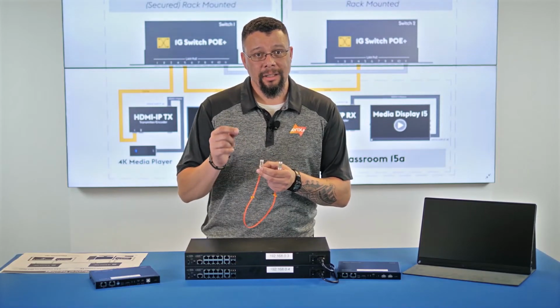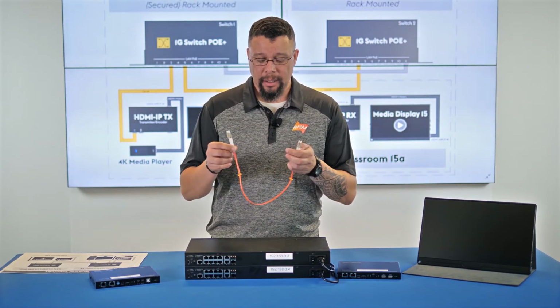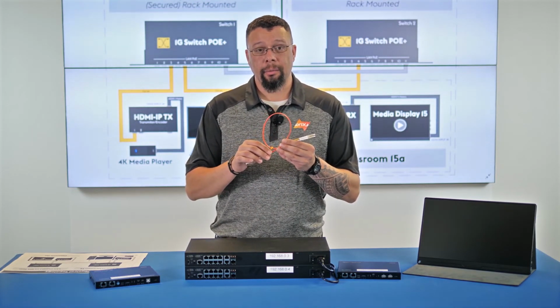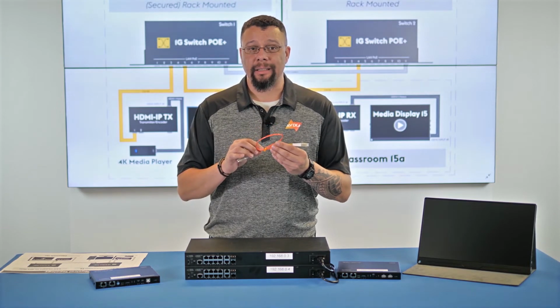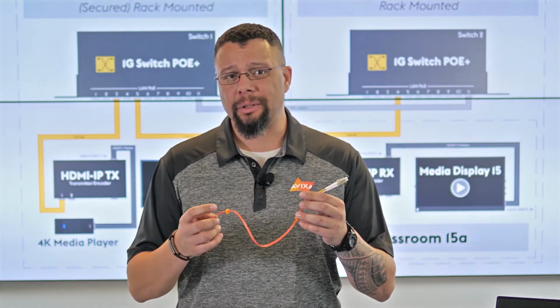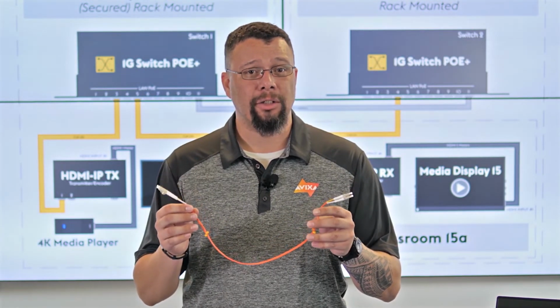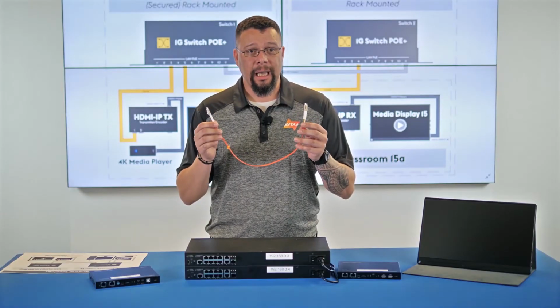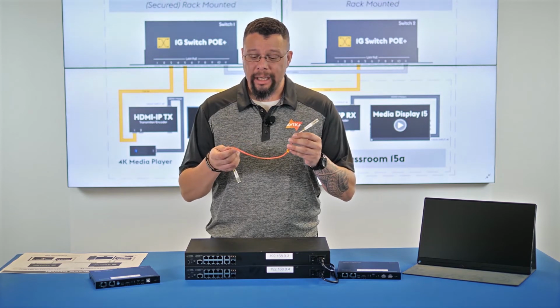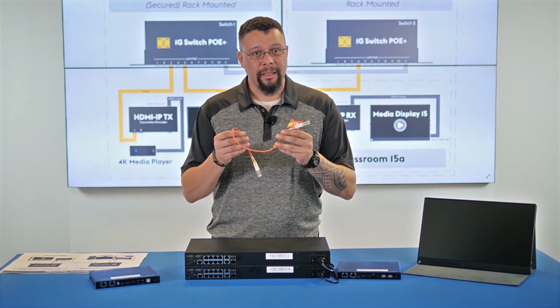Now pay attention to the optical cable's bend radius. Specifications will let you know what the maximum bend radius is. Bending too sharply will damage the cable since they are made of either glass or a very fragile plastic. Now this cable has about a 1-inch internal diameter bend radius.